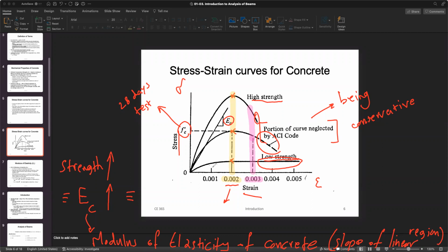But another thing is happening. The deformation is getting lower. You are seeing less deformation, right? As you can see, this tail is just getting closer to you. It shows the deformation is getting less. It deformed less, so we can associate that with ductility. So we can say ductility is getting less as well. That's another observation that we can study here.